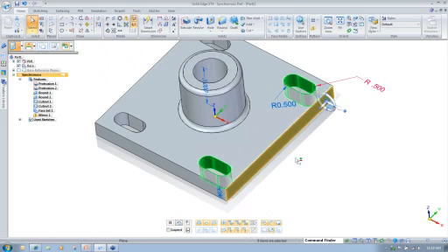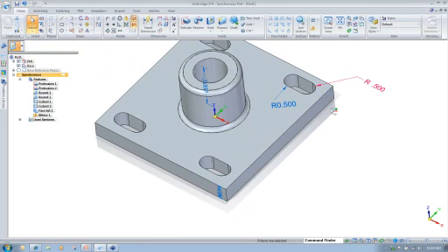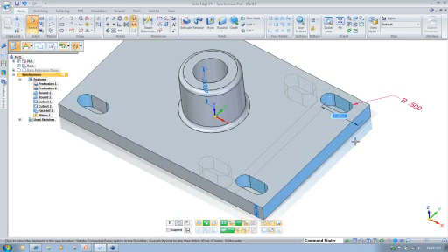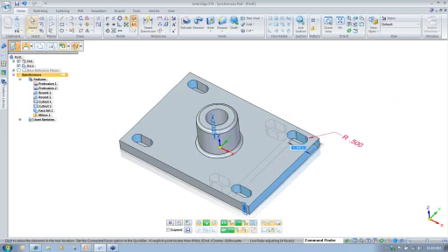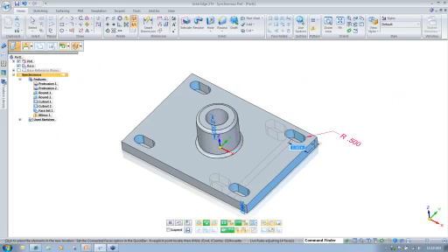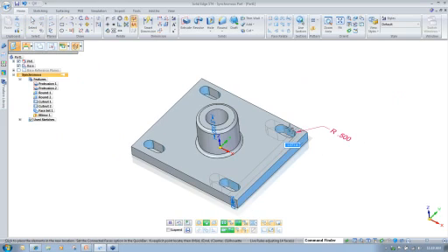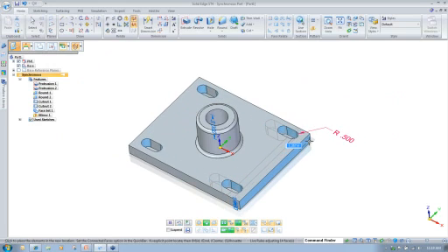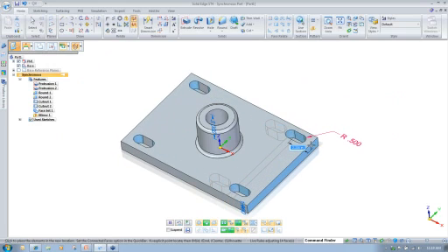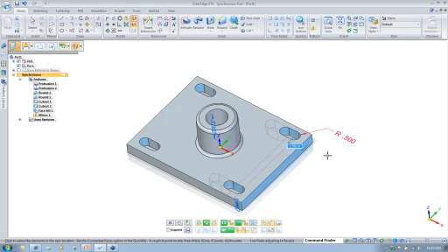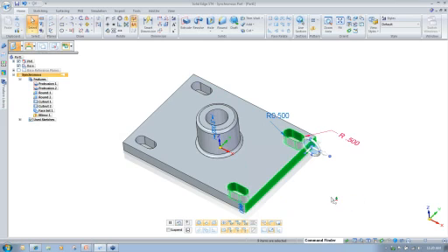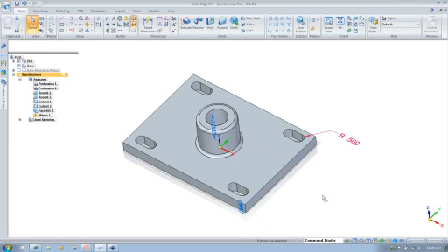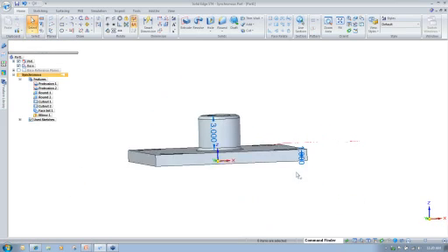So now that we have all that selected, I'm going to go ahead, hit my primary axis, and look to move. Now you can see that these are moving symmetrically and together. Both sides maintain the relationship of the slot to the edge. I'm going to go ahead and bump that out 2 inches. So now our mounting plate is continuing to take shape,